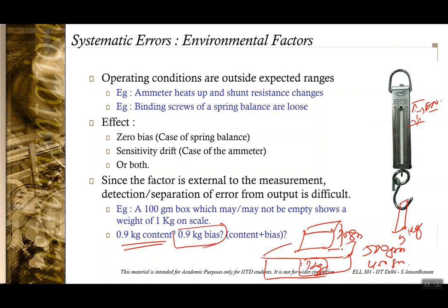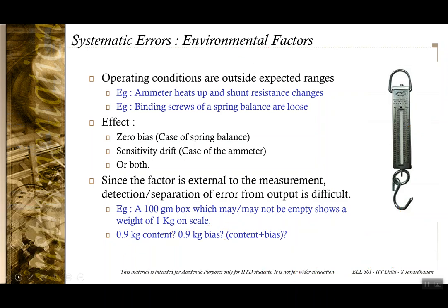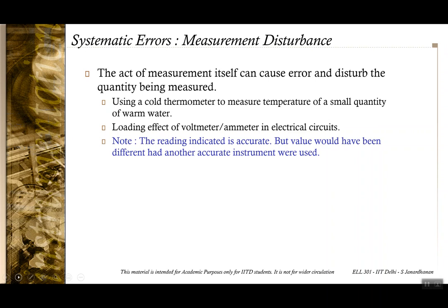So by just seeing this 1 kg and not really knowing the actual mass that is put in, you can't figure out whether the instrument has an environmental-factor-based error or not. What I'm saying is that this error is difficult to separate out unless it is calibrated against standard values or standard measures.